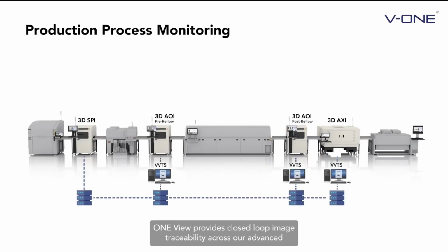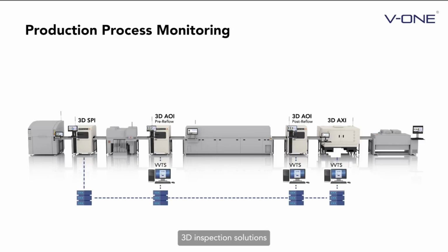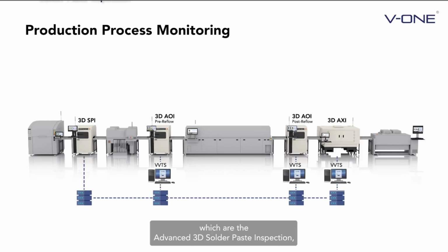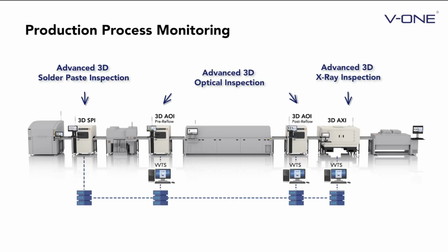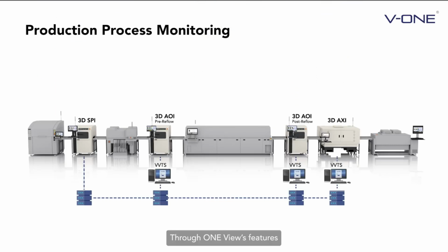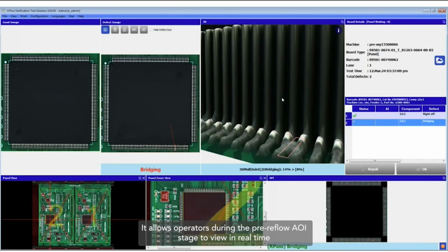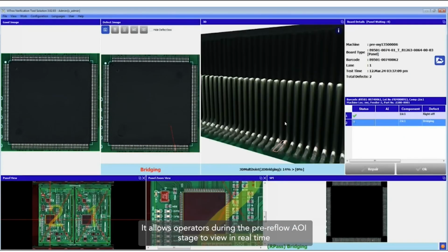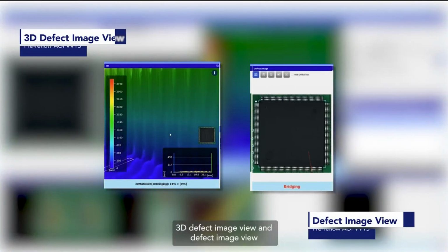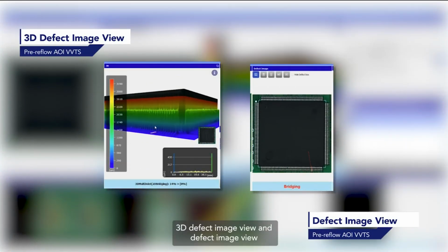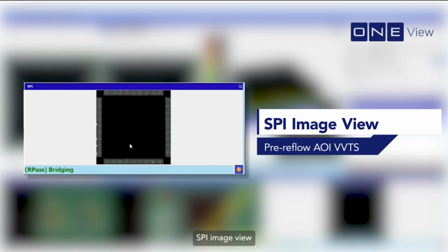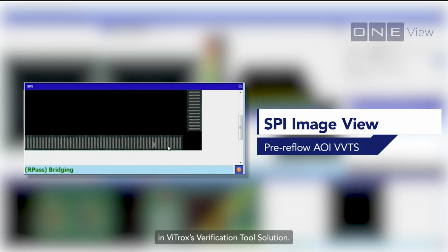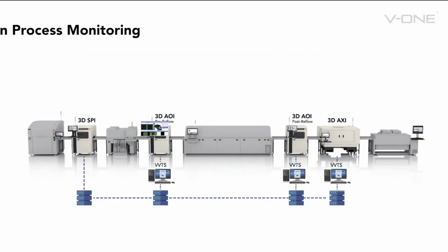OneView provides closed-loop image traceability across our advanced 3D inspection solutions, which are the Advanced 3D Solder Paste Inspection, the Advanced 3D Optical Inspection, and the Advanced 3D X-ray Inspection. Through OneView's features, it allows operators during the pre-reflow AOI stage to view in real time the 3D defect image view and defect image view, and specifically with the help of OneView, the SPI image view in ViTrox's verification tool solution.